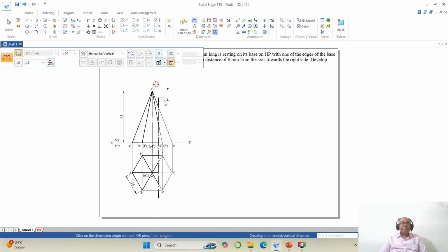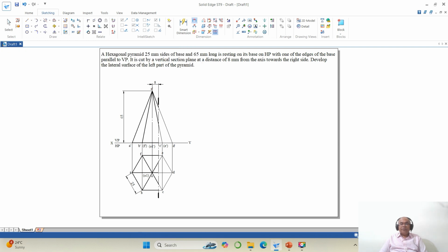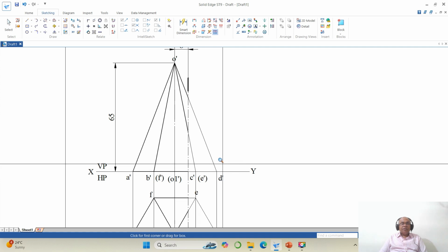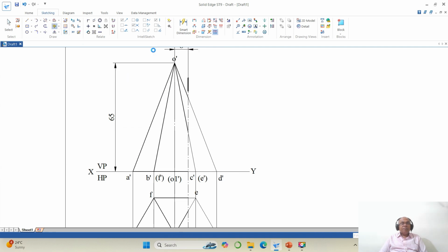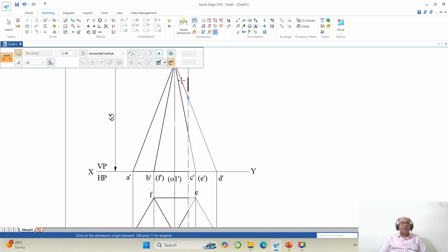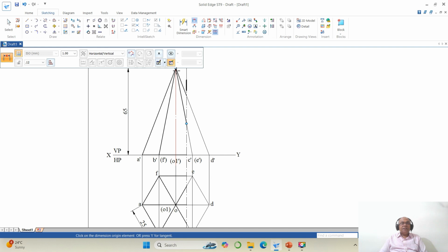8 mm. Okay, then you go to zoom window, then you go to move, select this, wait here, then go to distance between, you take this and take this, which is by 2 points.